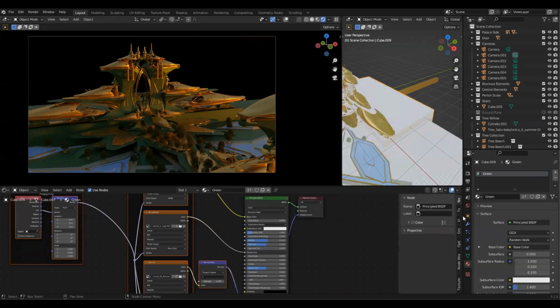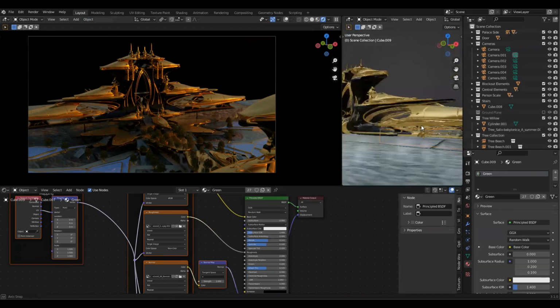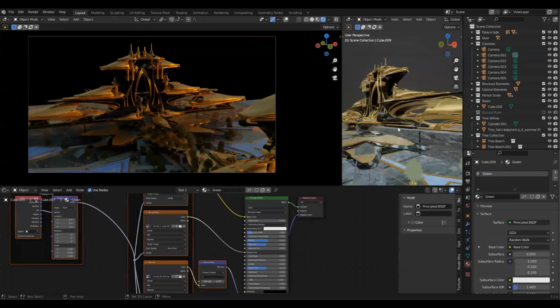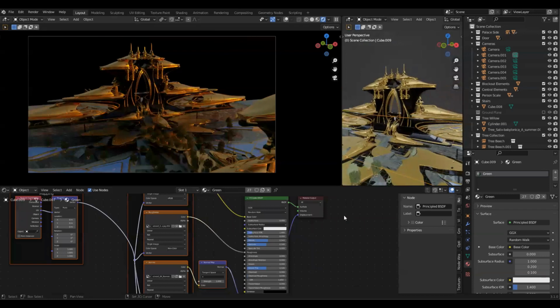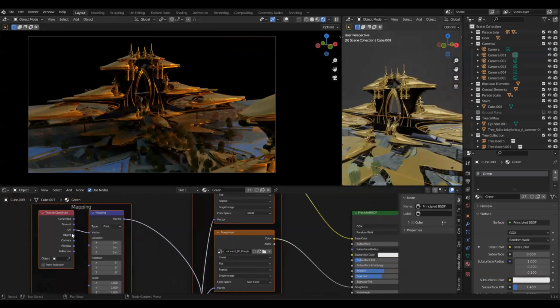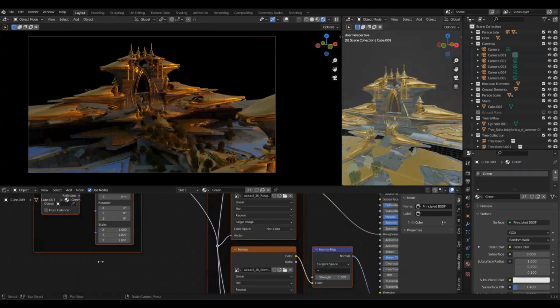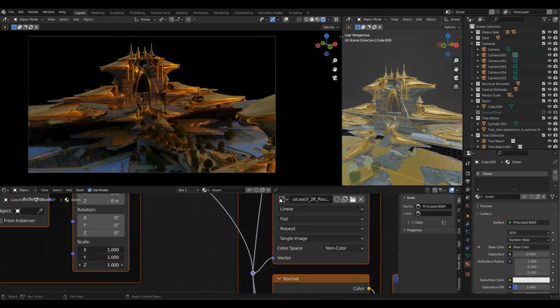And that'll take a second to calculate because we're doing this in the green material that's assigned to practically half the scene. It's going to take a second to figure out how that's going to work. There's a few errors here, but we'll get into how to fix that. So first things first, let's again switch this over from UV to generated, and unhook it there. Yeah, there we go. It just took a second. And let's click and drag over the scale and lower that quite a bit.